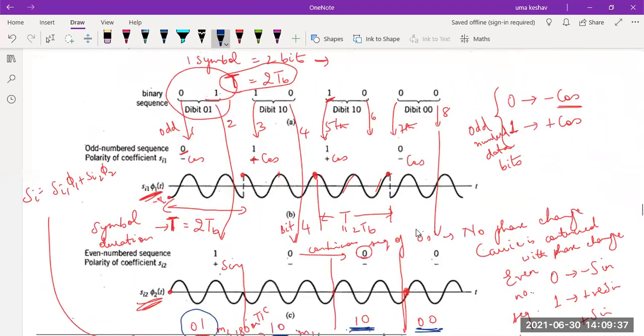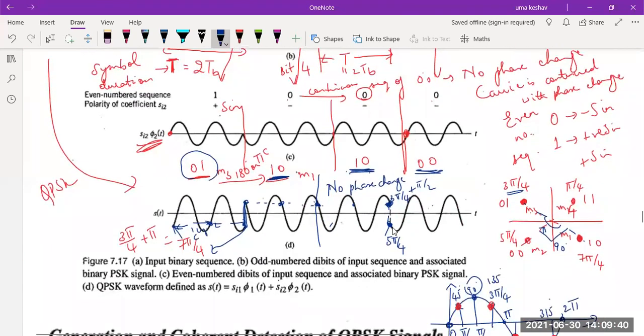You can see our signal also here. This last one is starting just before the negative minima. Till here we finished one cycle. From here to here, it is the second cycle. So we have represented the dibit pair 0, 0. This is how we draw the QPSK waveforms.